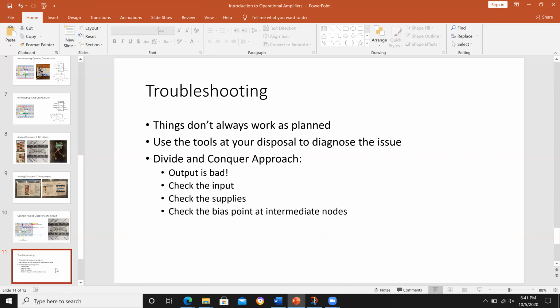The next likely is you're not applying the correct waveform settings. When I say waveform settings, I'm referring to how you bias your circuit and control it. The last thing is a bad component, which I've provided everyone with 3 op amps. So just swap the op amp out.